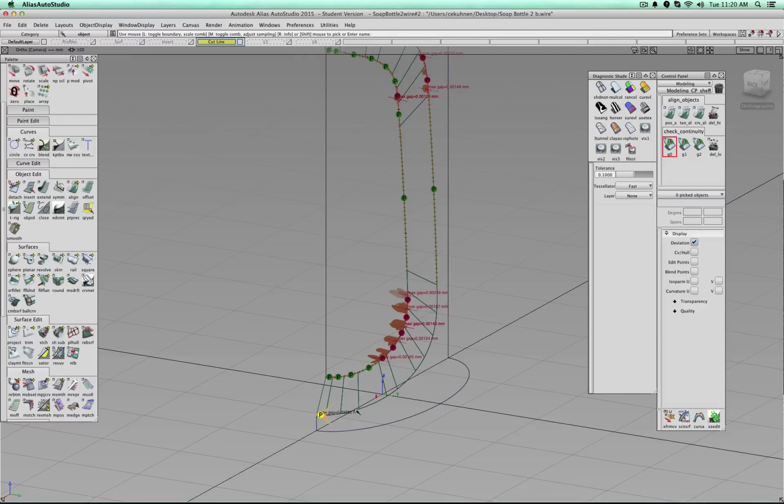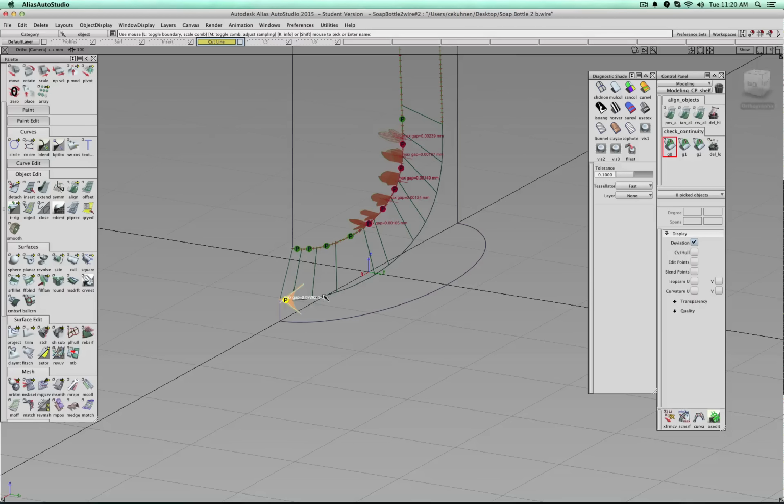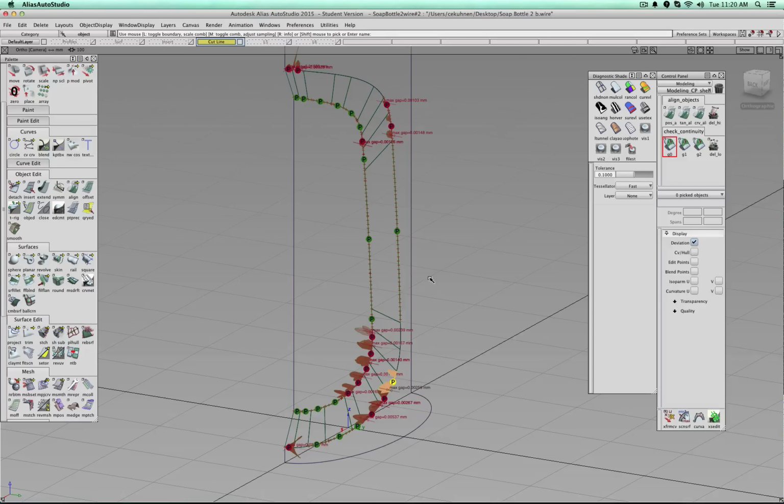And actually I have a lot of surfaces that don't match. Now, what could that be? Well, see, there are gaps, and the gaps seem to be too big. I could actually go back and when I had those curves, instead of a degree 5, make a degree 6, so I have more points.